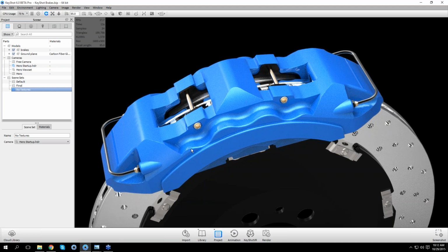When we're doing a very high quality rendering, something to think about with the CAD model are the radiuses and the filleted edges. Those are important, as you see here, when you have some nice highlights picking up on those edges. So when you receive the CAD data, does it contain those filleted edges, those radiuses? Does it contain NURBS data? In this case, this scene does have NURBS data.